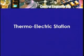The generation could be with a different prime mover. The prime mover could be a steam turbine. In the earlier days, it used to be steam engines, but no longer one uses steam engines, one uses steam turbines. So it's a thermoelectric generation. Now here it is the steam which has to be controlled. The pressure and temperature of the steam coming from the boiler has to be such that the generator will run at a constant speed so as to maintain a given supply frequency and a given supply voltage.